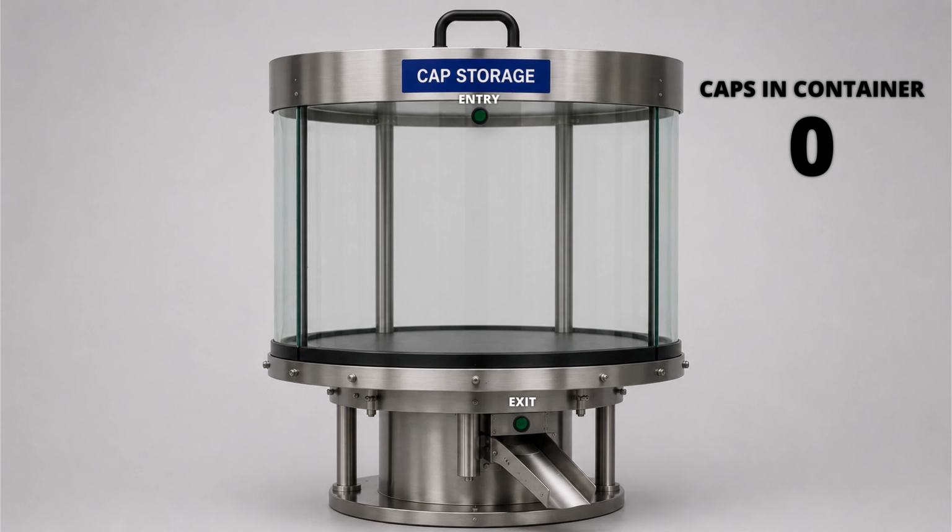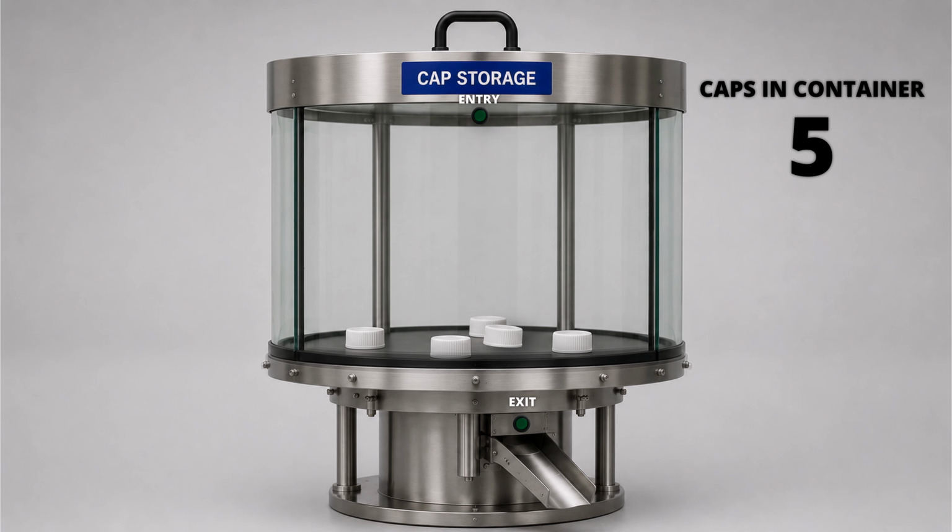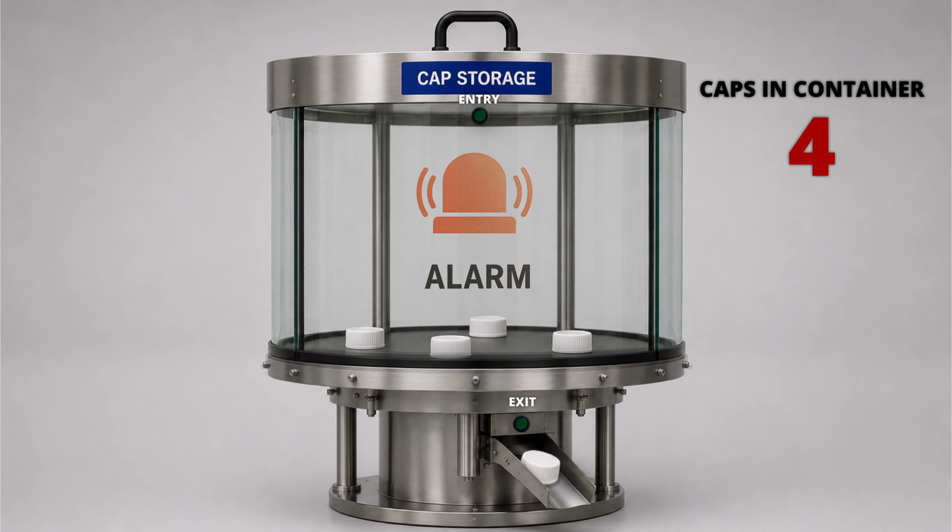So now we are going to compare the count of the bottle caps using the less than or equal to instruction, and generate one alarm whenever the number of caps remaining in the container becomes 5 or less than 5. By generating this alarm, we will decide whether to stop the production or put some more caps in the container. So let's create this program using the less than or equal to instruction.